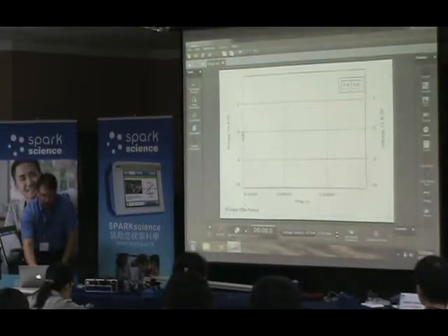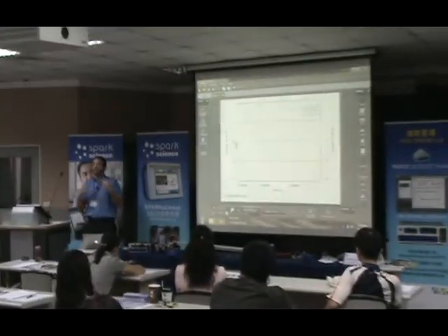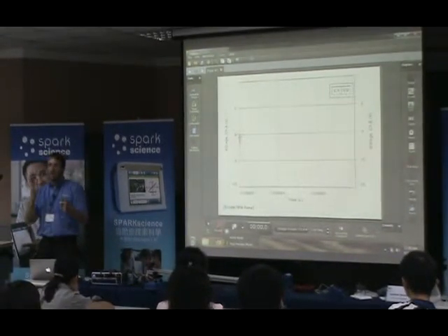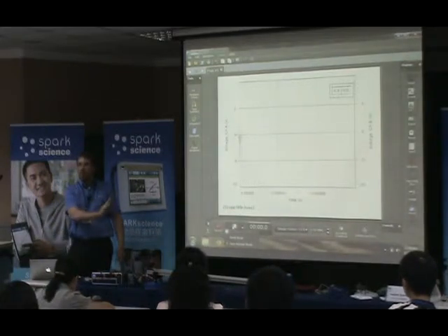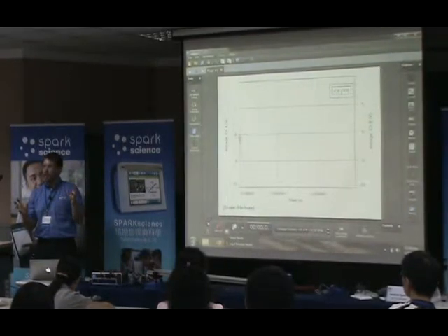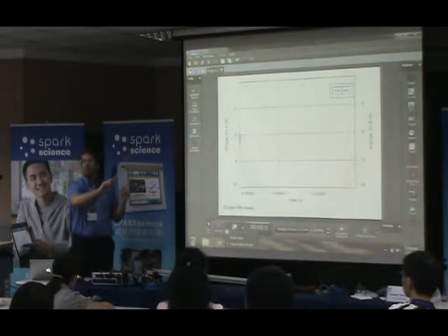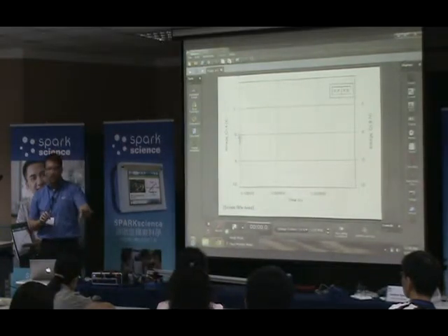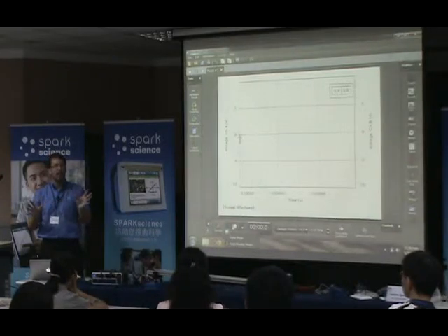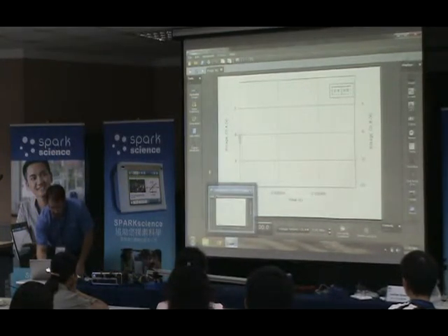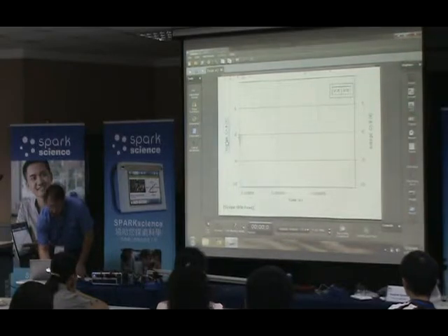All right, now one last thing I need to do is I need to switch to sampling mode. And so far everything you've seen today has been in continuous mode. And continuous mode means you start and it continuously takes data at a sample rate until you hit stop, right? In this mode, I'm not concerned about saving all this data as much as I am about seeing nice smooth plots of my signals. So I'm going to turn it to fast monitor mode. And that's going to allow the hardware and the software to burst their data at very high sample rates but not slow down the system trying to save all that data. Okay? So that's my first mode.